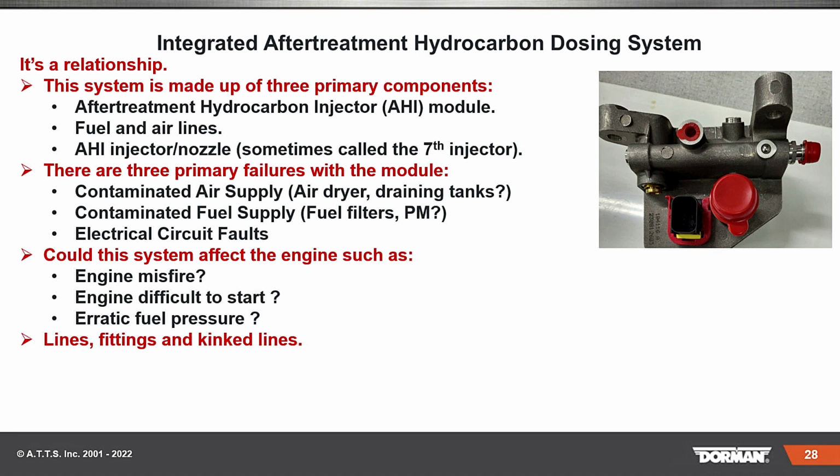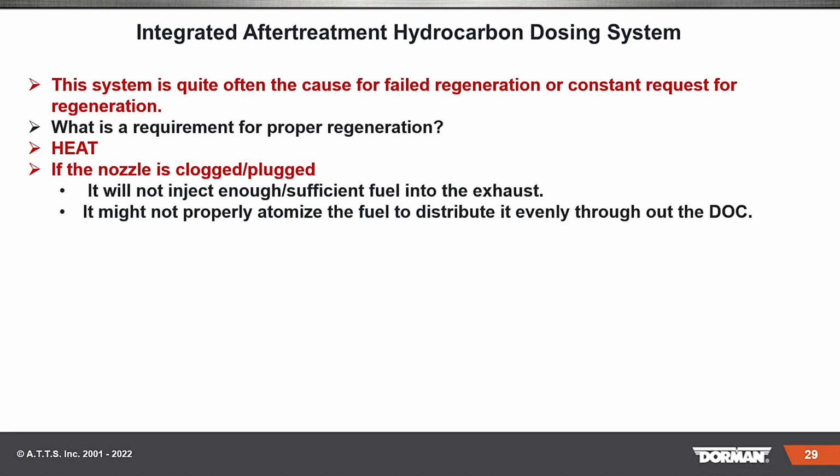And the point being is, could this system affect the engine? Absolutely. What if you have fuel leaks, fittings, and so on and so on? Difficult to start, and lines, fittings, kinked lines. So just keep that in mind. That's all. The system quite often calls for failed regeneration, a constant request. Okay, and again, why? What's the requirement? Heat, heat, heat, heat. So if the nozzle is clogged or plugged, it's not going to inject sufficient fuel. And of course, don't forget, it's not shooting out something properly atomized.